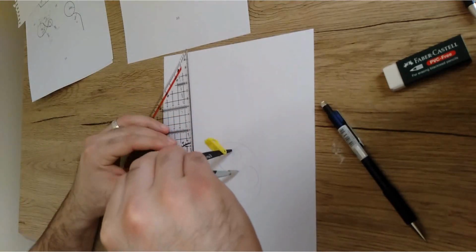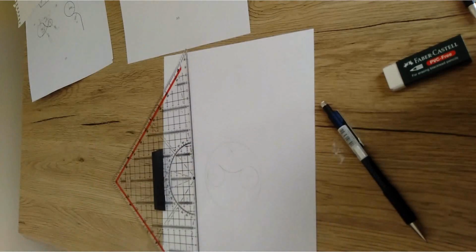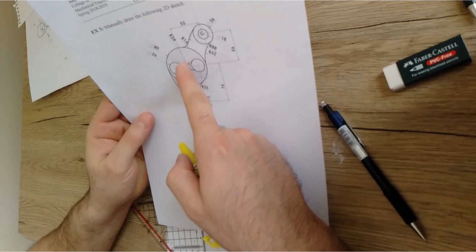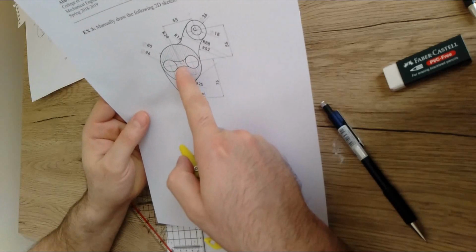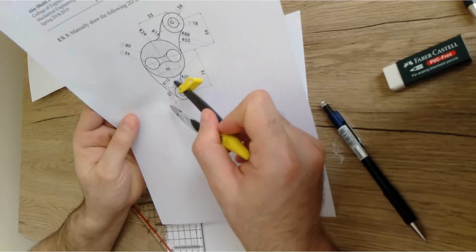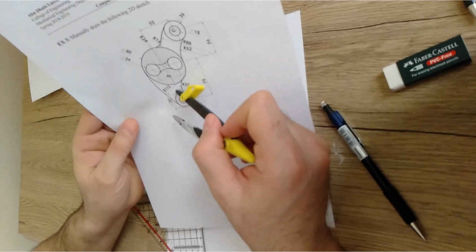If your drawing is accurate, you're going to end up with a perfect tangent as I already got here. How about the other curve? The other curve is identical to the previous one, right? So what does it mean? It means that definitely the center of the other curve should be somewhere down here, right? And it should as well be over this vertical line.